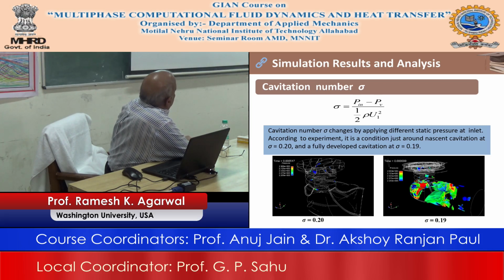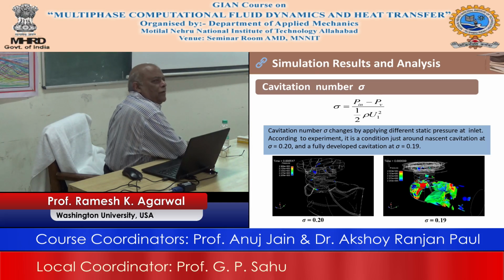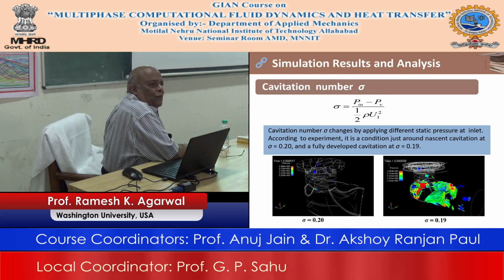Now the interesting thing about the cavitation number is that when it is 0.20, there is no cavitation, hardly any cavitation. It is just a small change to 0.19. The whole place is full of cavitation. And so this cavitation number is a very important number. Remember when I told you all the numbers, Bond number and Morton number and all that, I did mention to you guys that for some reason I forgot to add the cavitation number in that slide.